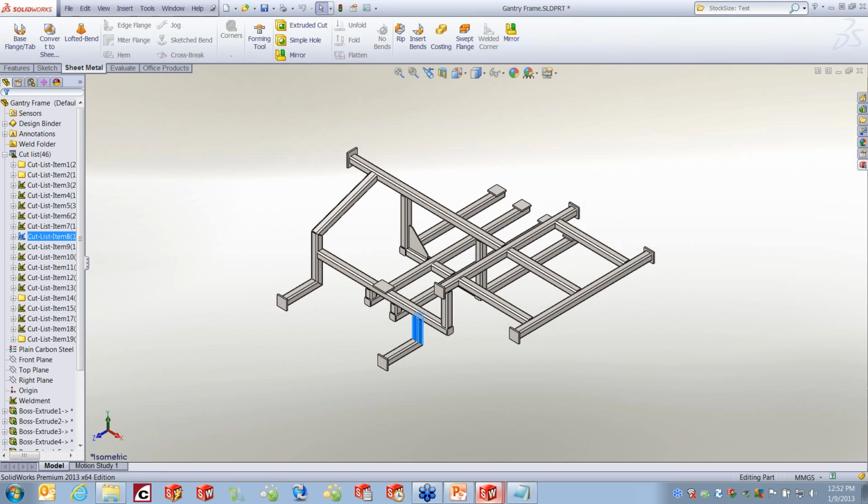Next question, with assembly visualization, what happens if the custom property is not in every part file? It just shows up as blank. It doesn't have to be already defined in that file. So let's say I had the material or description and never put it into the file. It will physically fill it out in those individual files. It doesn't matter if it currently exists or it doesn't. If you fill it out there, it's going to exist in those files. It's another method of filling those out.